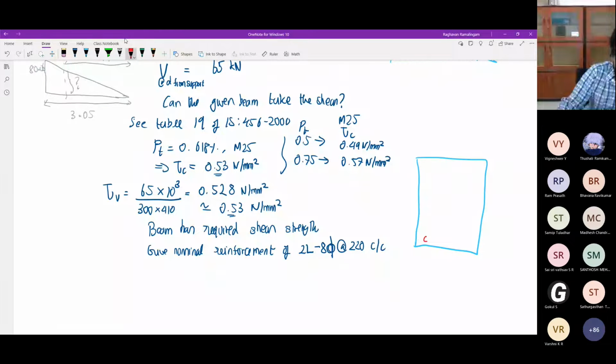So this is how you have to bend it. So it's bent from here, taken around this bar, brought all the way around, comes back, and then again bent over here. Okay. So this is your stirrup. Of course, when you place your stirrups, you should make sure that the clear cover is maintained. Okay, I have drawn it very quickly, but the clear cover should be maintained. It will be a straight line. It will not be a curve. It will be all straight lines. Okay, I have shown it like some kind of a curve. That's because I didn't draw it properly.